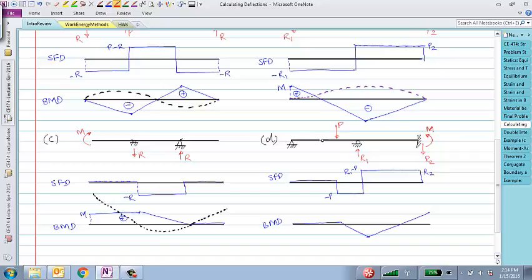Some bending moment out, some reaction moment out there, and that would be the positive moment M that we have out here, right? Make sense? Yes? No? All right, so another thing to notice here is that we have this point where the bending moment goes to zero. What is that called? Point of inflection, where the curvature changes from positive to negative, right?